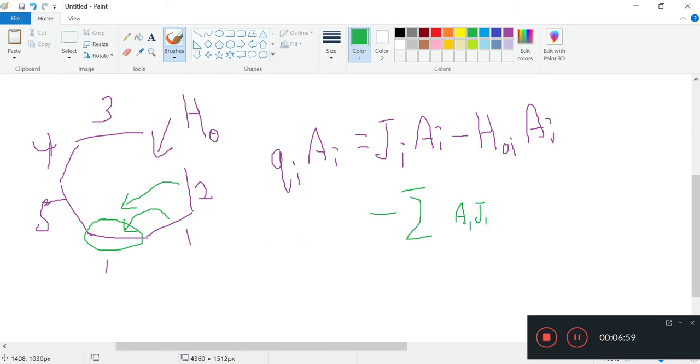This is the total heat coming off that, and you need a view factor from 1 to i. If we do the same for not just surface 1, but 2, 3, 4, 5, and so on, we will end up with this. So instead of A1, we denote it A_j because it is the surface that isn't i.